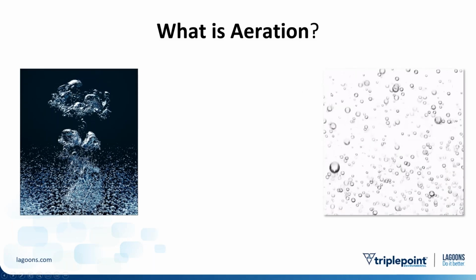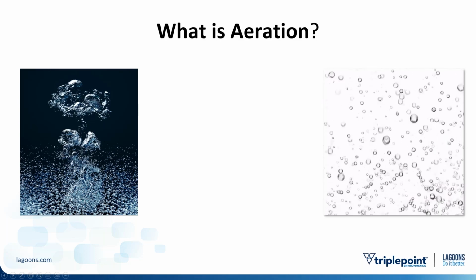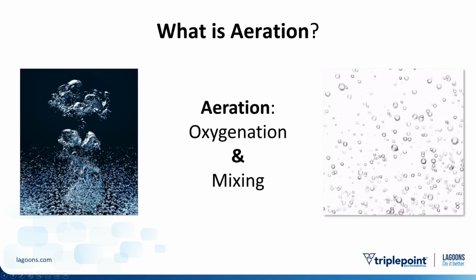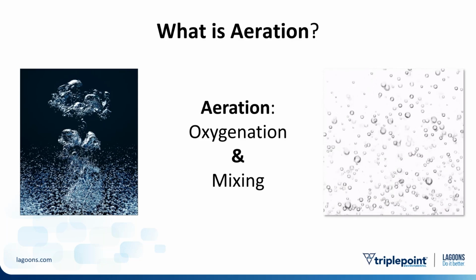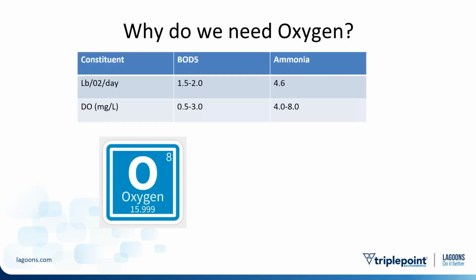So what is aeration? Aeration, as you probably know, is not just adding oxygen to water, but adding oxygen to water and mixing the water such that the bacteria, the waste, and the oxygen are constantly in contact. We can't forget about the mixing component of adding oxygen to water.